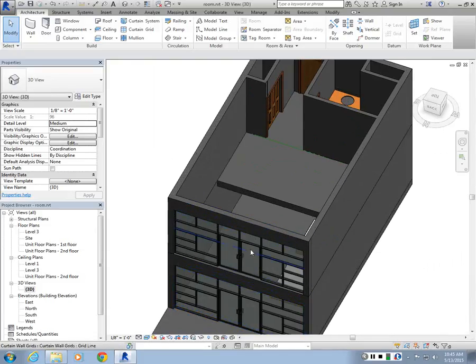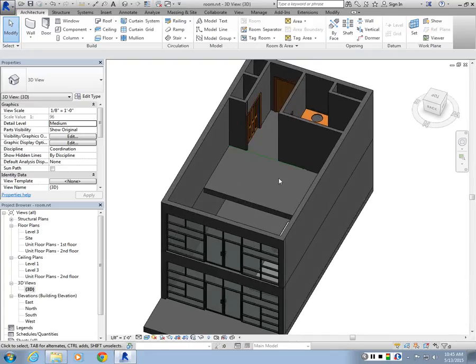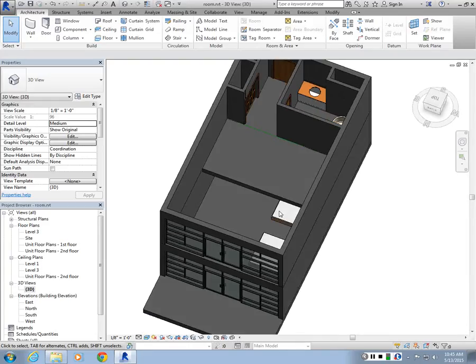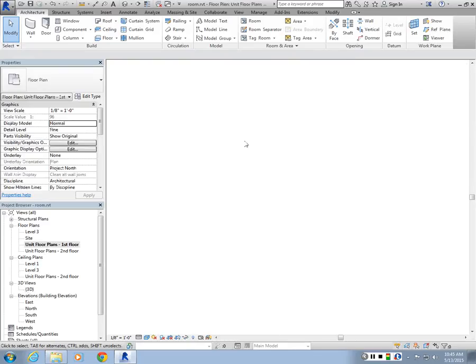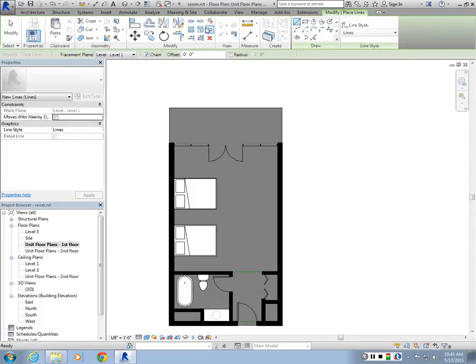And I would probably delete this, or you can extend this curtain wall to go up to this level and do a custom subdivision again, as you may want. For this assignment, I haven't shown stairs yet, so just leave a space for stairs. You can add them later on, okay? Or you can just sketch it with model lines. So the model lines are here. If you go to architecture, model line, it's basically, you can use it for drafting, right? So you can draft something